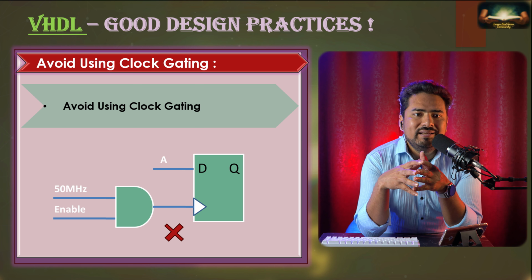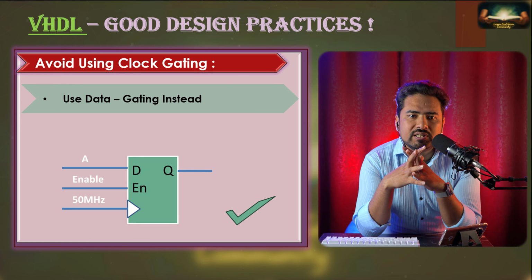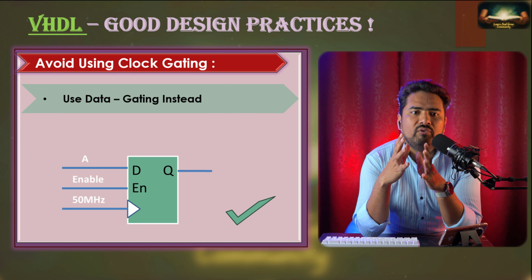So your clock signal remains unaffected by any logical gate delays, and it is directly reaching your flip-flops without any additional component between them. So this system has better timing margins compared to the last one, and it can operate at a higher clock speed as well, meaning better operating frequency. Even some FPGA architectures provide flip-flops with dedicated enable pins, like in this block diagram. In such cases, your synthesis tool will integrate that without any additional component.